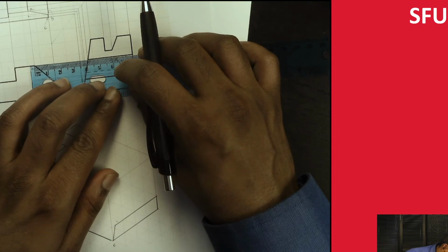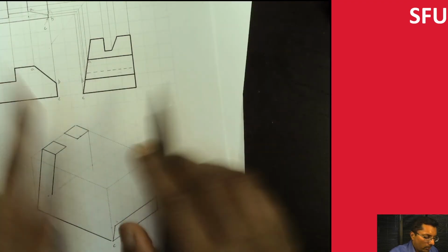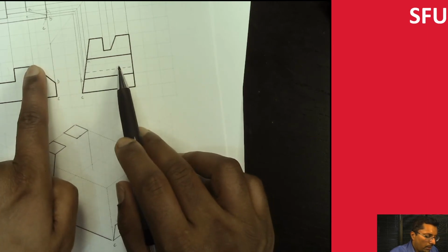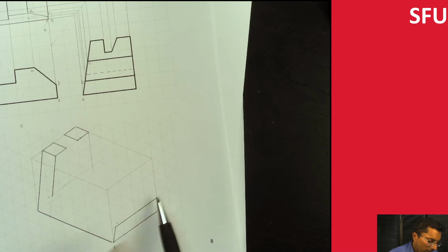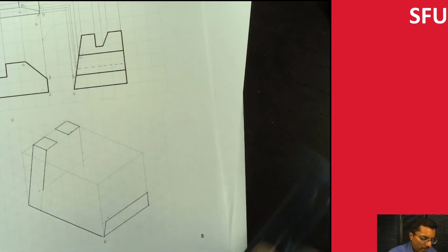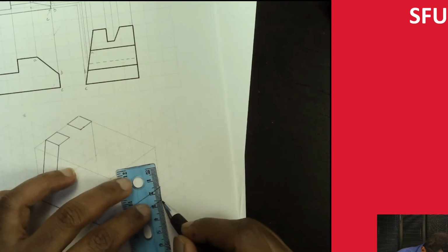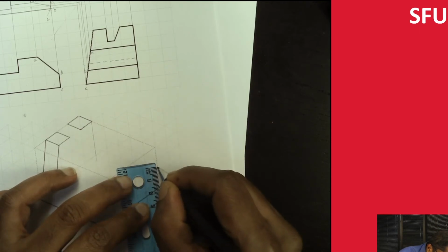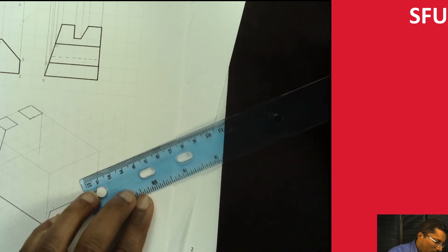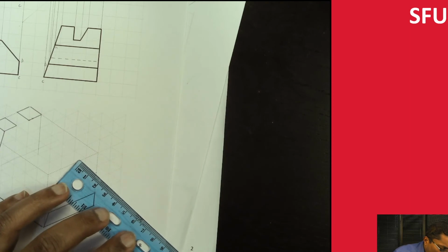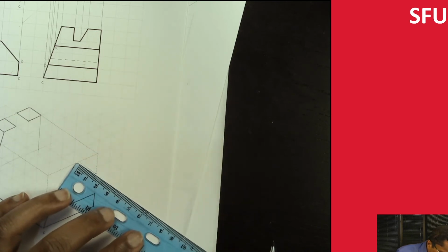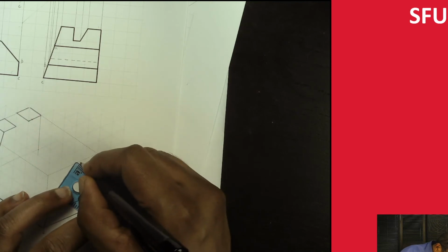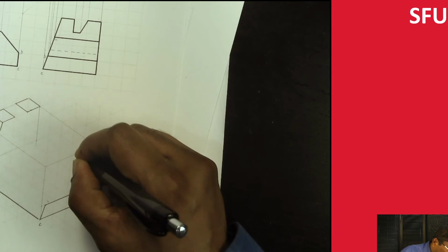This is 15 millimeters. So how do I do that? Essentially I'm going to go 25 millimeters up. That'll give me this point, and then 15 millimeters to, basically, the left side of the object. So this is 25 millimeters up, and let's actually measure this out. Then we're going to go 15 millimeters in, basically doing this towards the left of the object. Again, I need to make sure, maybe I draw another helper grid line on it. Up over here, it's going to be essentially here.